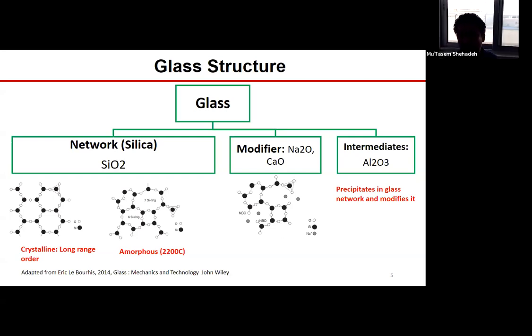Yeah, but here the issue is that glass is not crystalline. It is amorphous, and here we're not talking about deformation processes. Rather, we're talking about fracture. So the issue here is related to crack propagation in such materials, the branching behavior. However, there is some plasticity that is observed at a very small scale in these glasses that will lead to what we call damage accumulation, which can be used to absorb some of the energy in such samples.